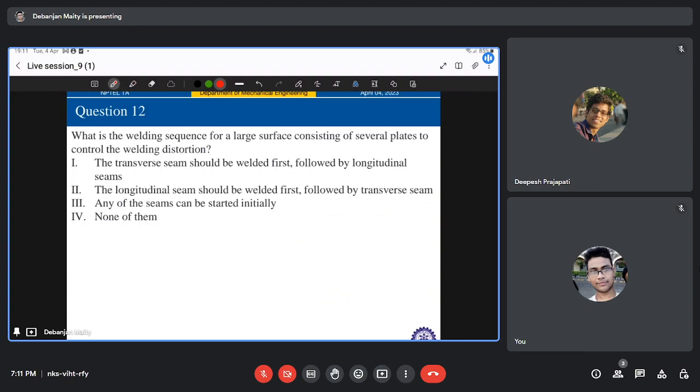Now, second, what can be done? You can prepare your joint properly, right? Especially for unrestrained butt joints. If you are preparing it properly, you can minimize the angular distortion. Like, you can use a double V or W, basically you can do the double thing as opposed to the single V or single U configuration, to balance that heat input or shrinkage. Thirdly, you can use minimum sized fillet welds.